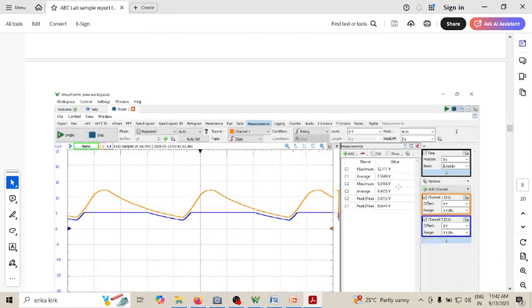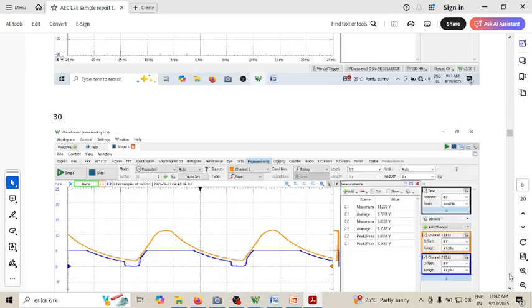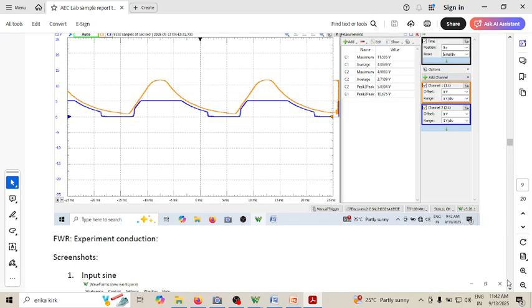Then can you see here, suppose you further reduce the resistance to 50 ohm, when I reduce to 50 ohm, can you see the output average has reduced from 4.9 to 4.4. So now output has reduced to 4.4. Now this is a resistance of 30 ohm. Can you see the output average? Can you see it has become 3.5?